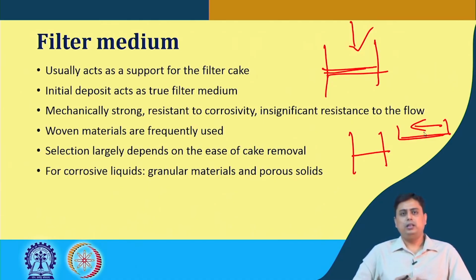So, this filter medium has to be strong enough to withstand high throughput of the suspension, as well as the weight of the cake and the impact of the particles and the suspension. It should be resistant to corrosivity, and ideally it should have an insignificant contribution toward the resistance to flow, because it is the initial deposits of the cake which will act as filter.